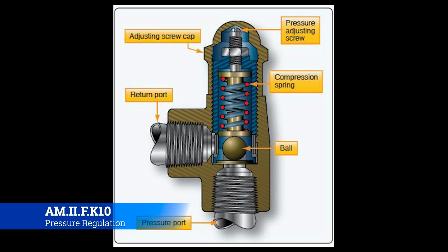Now, this is something that you will do every time you install a new hydraulic system, or even certain components of a new hydraulic system, into the aircraft. You'll make these little adjustments often, sometimes even with just a jeweler's screwdriver. It doesn't take a whole lot to change the pressure in your hydraulic system with one of these pressure regulator valves. But this is a way to try to maintain the pressure at a stable amount that doesn't get too high, doesn't get too low. It's right there.